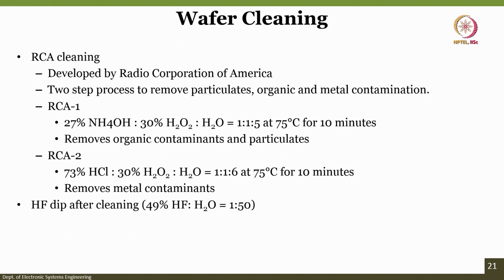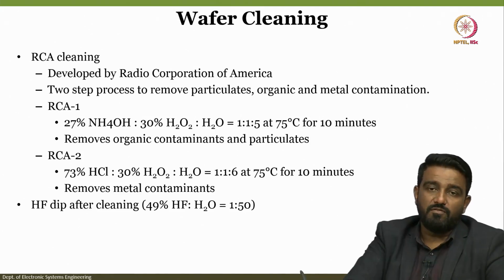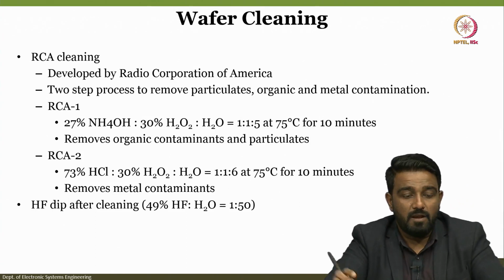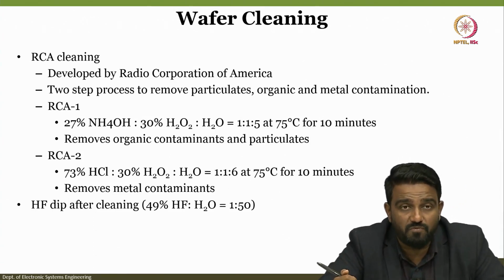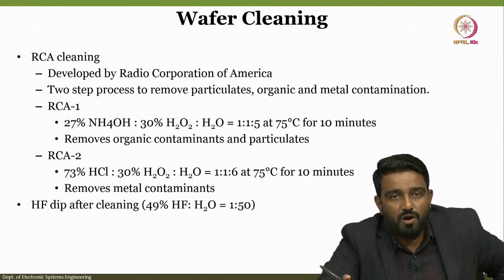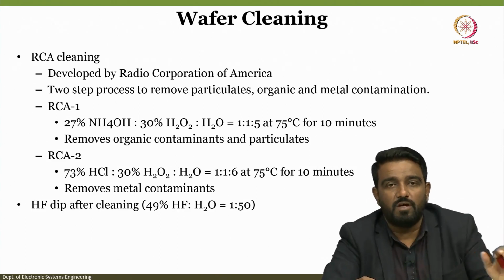There is something called RCA cleaning, RCA1 and RCA2. RCA stands for Radio Corporation of America, and there are two steps to remove particulates, organic and metal contamination.